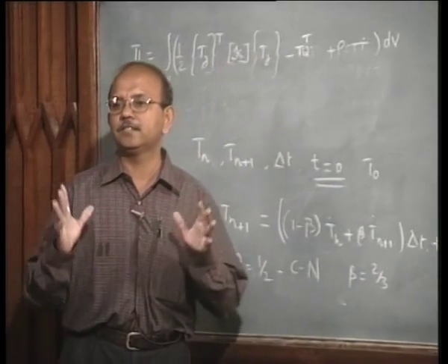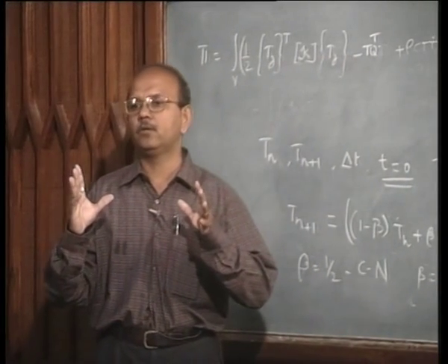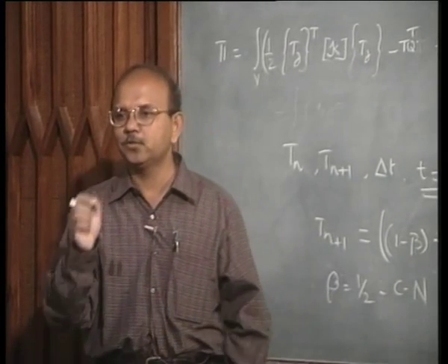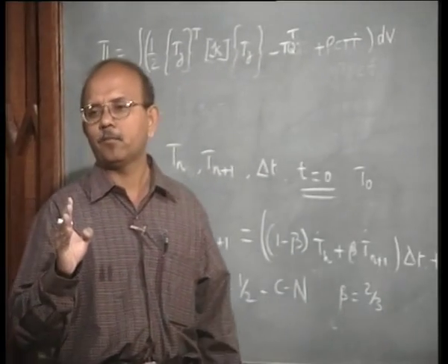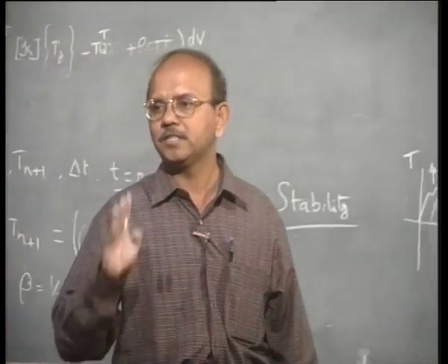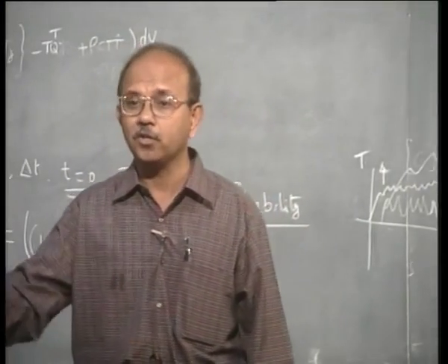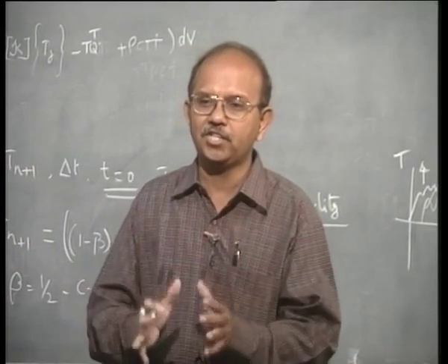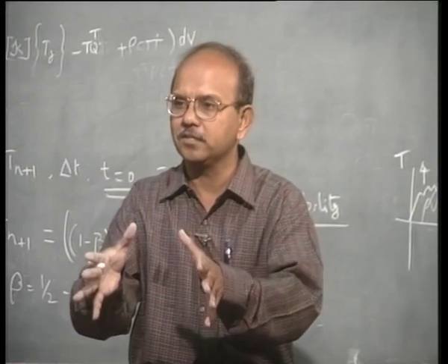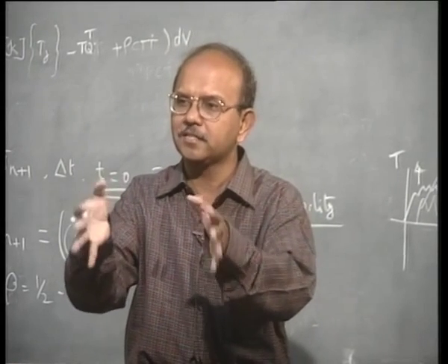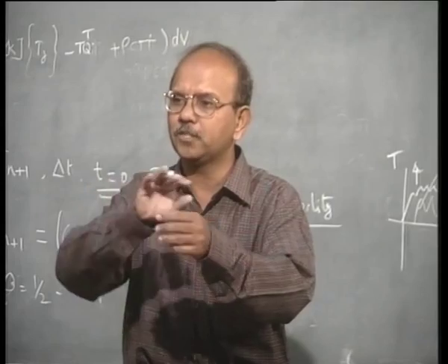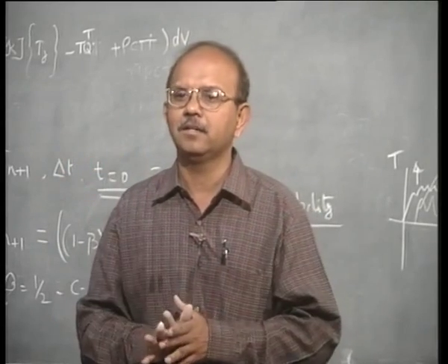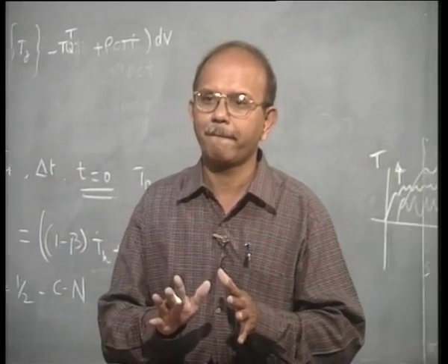He said Crank-Nicolson scheme is the best scheme I studied, so why is it giving this? Why does the scheme give rise to oscillations? Please note that this is the problem, because people get confused between stability, oscillation, and accuracy. All of them are different things. The Crank-Nicolson scheme, especially when you start, would result in oscillations, but will give you a very nice accurate result. If you smoothen or dampen that out, you will get a nice result, but there will be an oscillation.